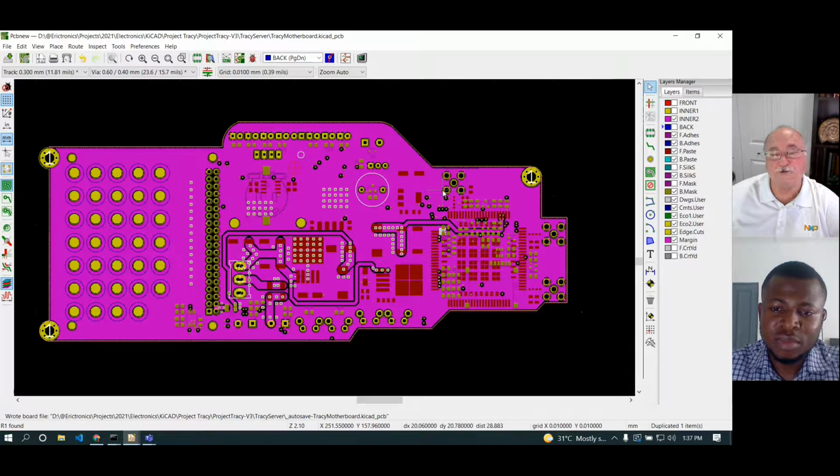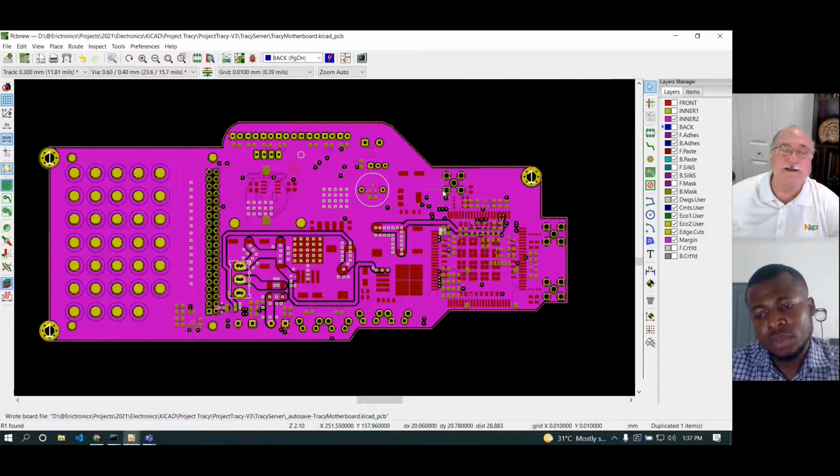I know that most often there isn't this luxury, but what I find is on the input power circuit for most boards, from the connector to the voltage regulator, in that space, there's rarely any other signals routed. So you have the opportunity to go from the wiring connection to the voltage regulator with these parallel dielectrics and to improve that movement of energy from the first capacitor next to the wiring harness into the voltage regulator. That helps to reduce conducted and radiated emissions.